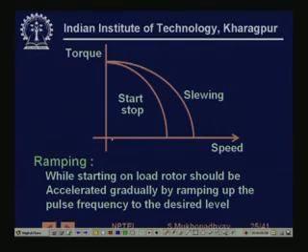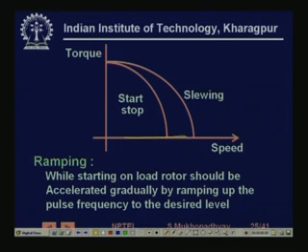So therefore we cannot just have more and more speed just by increasing the switching frequency of the phases. That is not possible. So it turns out that while we are trying to start the motor, we have to start it slow, when you are giving pulses at lower frequency. Initially it will come and then it will stop, then you will give the next pulse, so it again starts moving. So you slowly start increasing your pulse frequency, so that the motor gradually starts slewing.